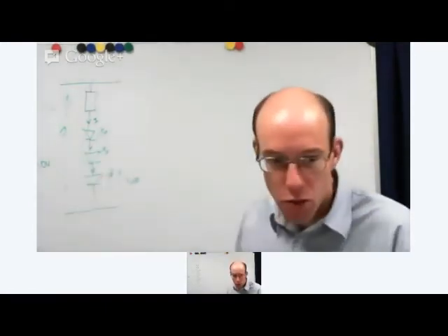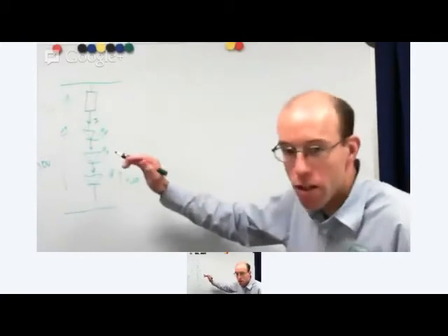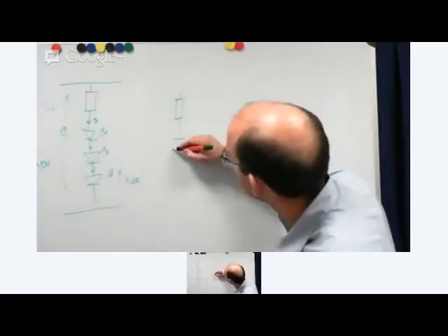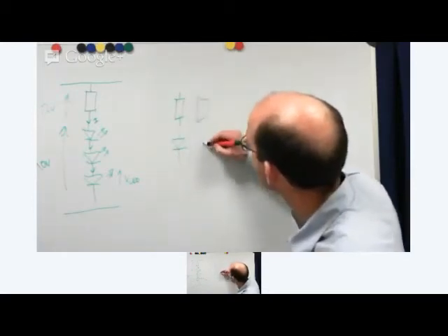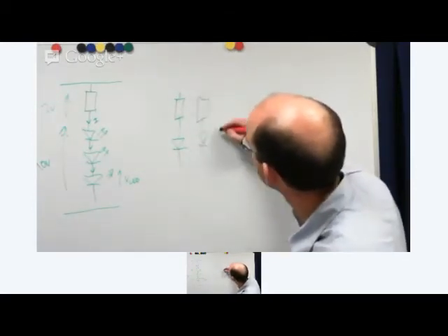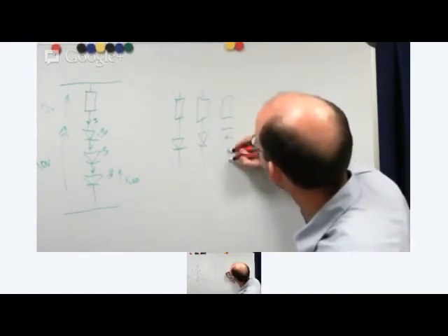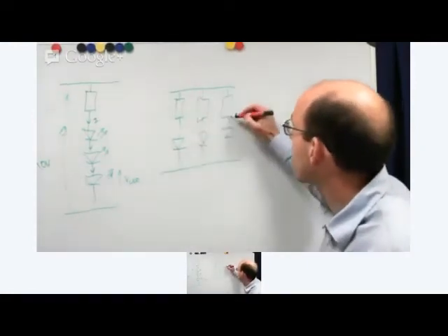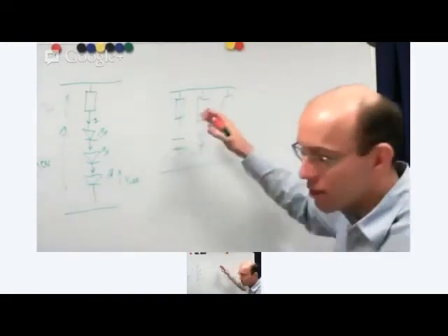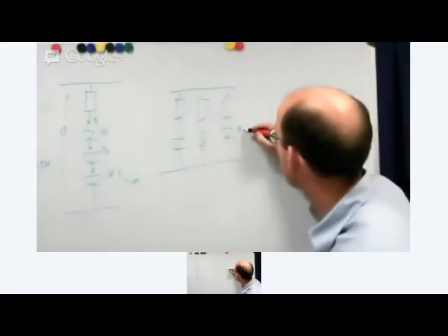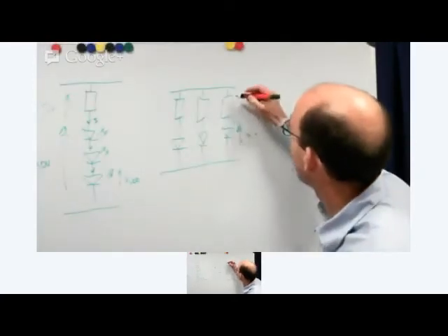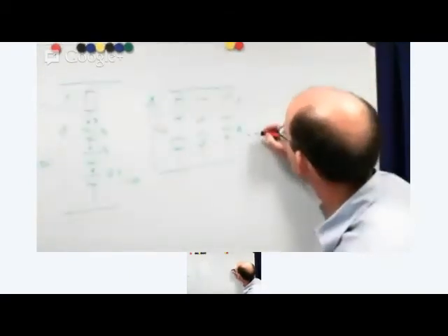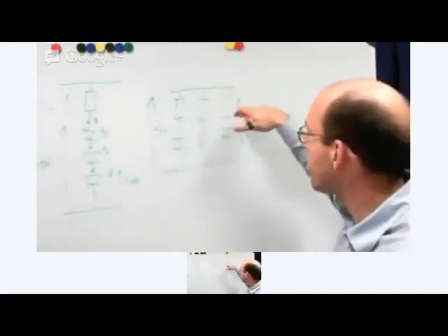So if we wanted to do that same circuit, but as a parallel connection, what we'd need to do is, in theory, the best way of doing it is to supply one current limit resistor for each of those LEDs. Like that, and we can work out what the current limit resistor wants to be, again using the same logic. If that's 3.3 and we want 5 volts across there, then we're going to have 1.7 across there, and we can do the maths again.